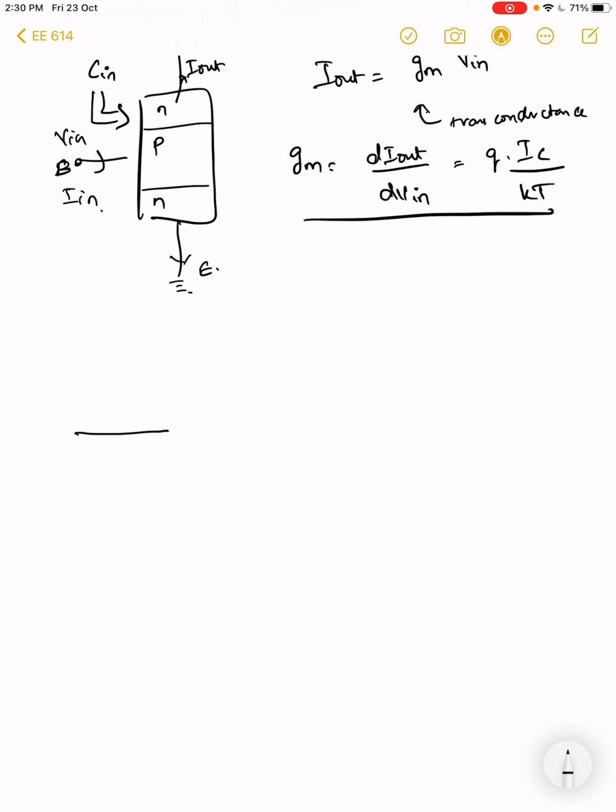Under this situation, we know about certain capacitances, right? You know that your collector base has a capacitance. This is C depletion collector base, depletion capacitance, right? You have an emitter base depletion capacitance, right? And we saw that because of the minority carriers here, a PN junction has a diffusion capacitance. Why is there no diffusion capacitance in the reverse bias base collector junction?